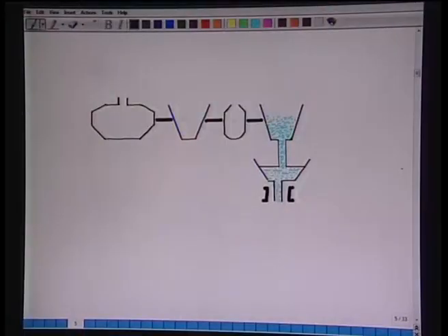Now, after this, let us see the iron and steel industry where the refractories are used. Here I have just shown a schematic sketch of various vessels where refractory materials are used. The first one is a torpedo vessel. Now, this torpedo vessel typically handles hot metal from the blast furnace and transfers it to the LD steel making.